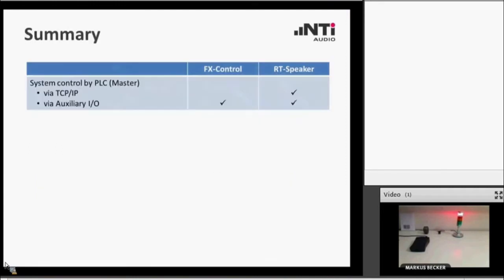And summarize what we have just shown to you. We had the two software packages, FXControl and RT-Speaker, and you have seen how to remote control RT-Speaker through a TCP/IP link, so how to remote control the system by a master PLC. Then we have also shown you the auxiliary I/O interface, how it can be used, for instance, to trigger a test.